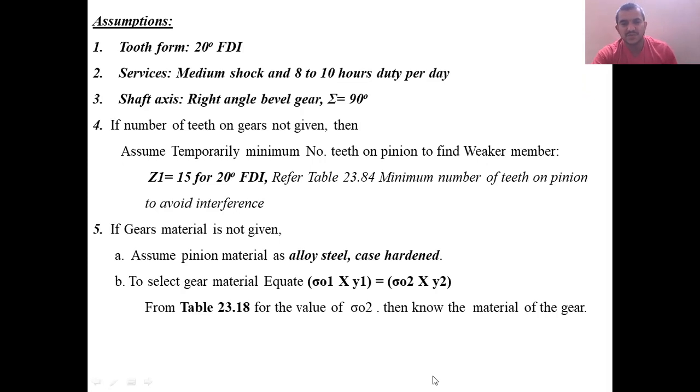Next, these are the assumptions we should follow. What is the first assumption? If the shape of the tooth and pressure angle are not given, then you assume 20-degree full depth involute. Then what type of service here? Medium shock, 8 to 10 hours duty per day. The shaft axis is a right angle bevel gear. Consider the shaft angle as 90-degree.